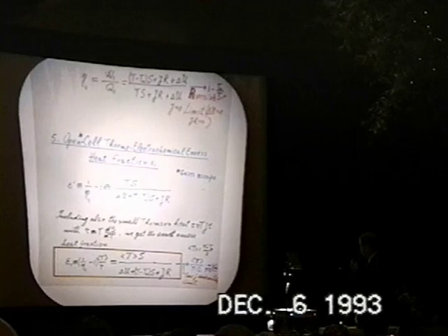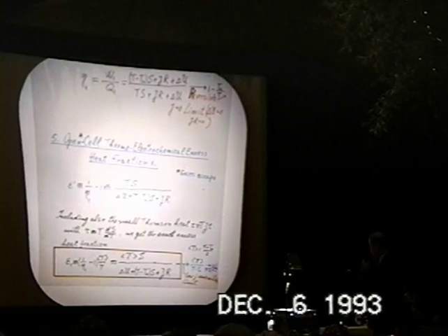If we introduce also the Thomson heat, then actually what we need to do is multiply this result here by the ratio between the average temperature between outside and inside. This means what would be in the middle of the insulating wall of the calorimeter, that's the T average, divided by T on the hot side, that's inside.